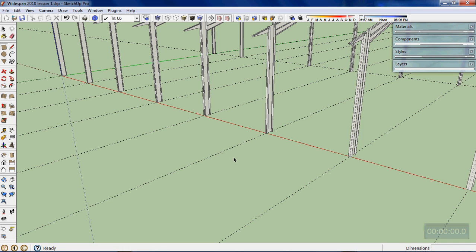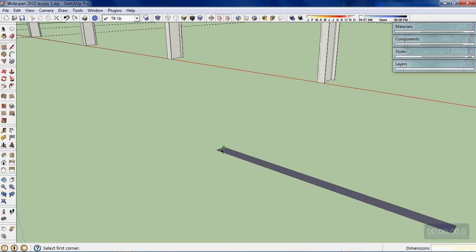So for now, out in space somewhere here, not connected to anything, I'm going to draw a rectangle, and just like I say all the time in SketchUp, you can actually just sketch something roughly the right proportions, and then after you've sketched it you can type the real dimensions. The real dimensions in this case, I'm just going to start with some length of the wall, which would be 3000, comma, for the other direction, 149.8. So I've now created a rectangle 3 meters long by 149.8 millimeters wide.